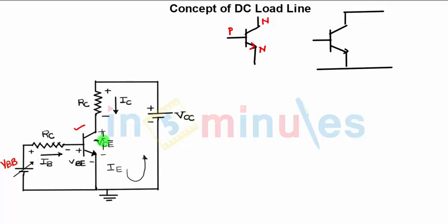Right, now how to identify the various terminals? I mean to say whether it is common base, common emitter or common collector. Once you identify the terminals, you can easily identify which configuration it is. Now this arrow is from base to emitter, right? So this is your emitter, this is your base and this is your collector. This is your input port and this is your output port.